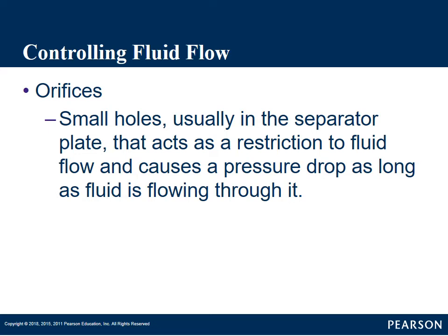But in some cases, even for hot rodding use on the street, that just makes the shift really, really hard and really uncomfortable. So a lot of times in those cases, we'll just drill that small hole out a little bigger. But those orifices are small holes in the separator plate that actually control how much fluid pressure is applying.